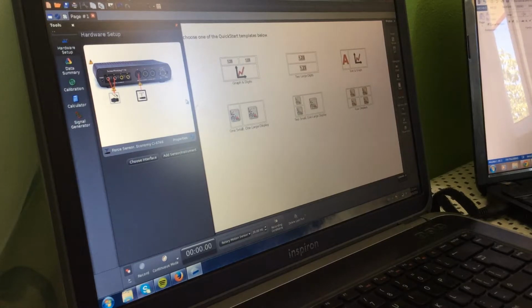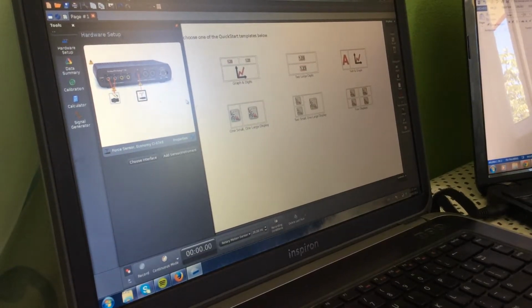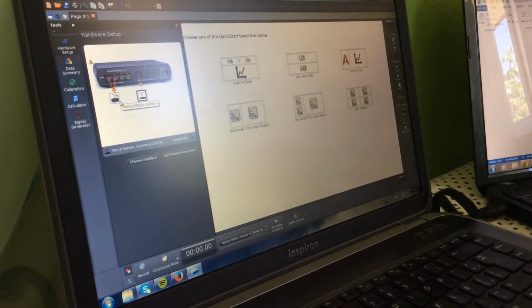To configure this sensor, we must consider which port is physically connected to the interface. For example, if I have connected the rotational motion sensor on input 1, we click and look in the list for the corresponding sensor, which in this case is rotary motion sensor, and we can see that the selection appears. We join it with two lines that indicate that it uses two digital inputs. In this case, the connecting lines will be red with a yellow symbol, saying the sensor is not in place.